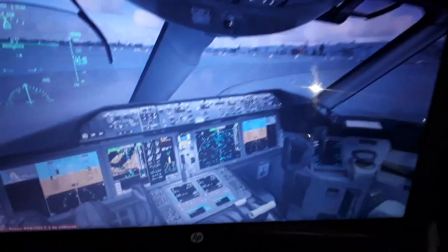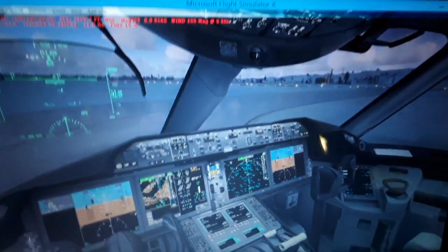Also the fuel flow per hour, oil pressure, oil temperature, oil quantity, and the vibration of the N2 stage of the engine. Also it controls the outflow valves of the 5th and 9th stage, and the bleed from the engines, from the bypass. We supply the cabin pressurization, oxygen regulation in the cabin, pressurizing the cabin, and also hydraulic fluid tanks pressurization and wing and engine anti-ice. So we have many systems supplied from the engines pressurization.